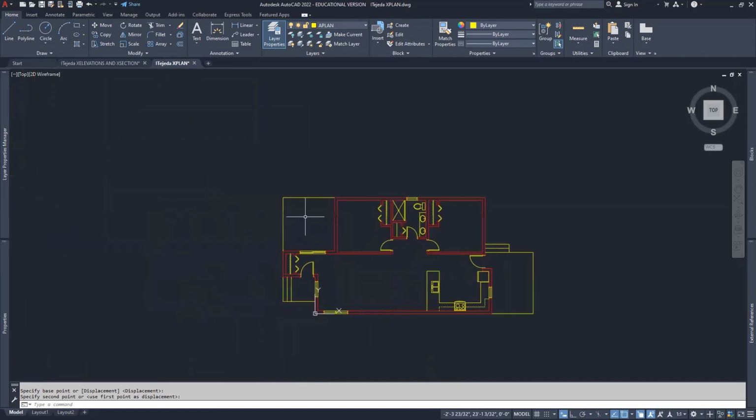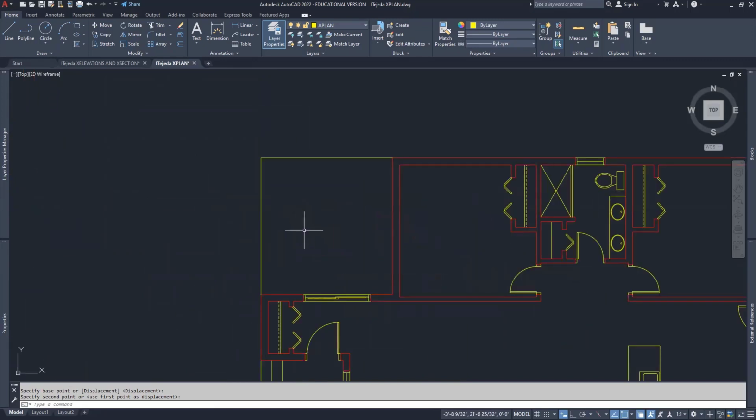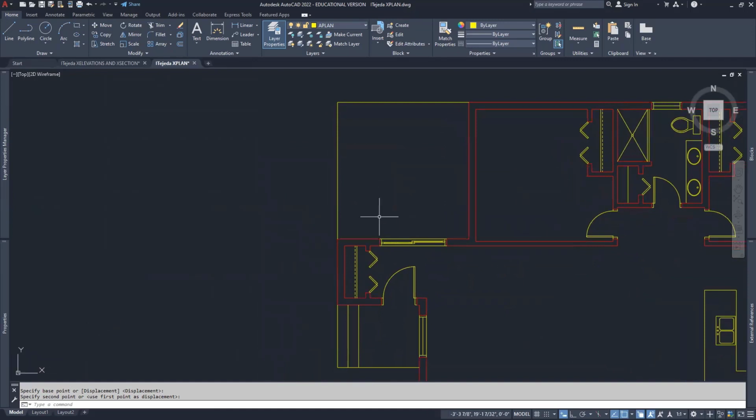And now over here on the stairs, I think I want to do something that is somewhat symmetrical to the entry stairs. I want to have a set of stairs and I want them to be as wide as the ones that are here. What I'll do is I will type MI, enter, and I'll take the 2 lines and this one and enter. And I'll take it from the midpoint here of that wall and take it over and then click.